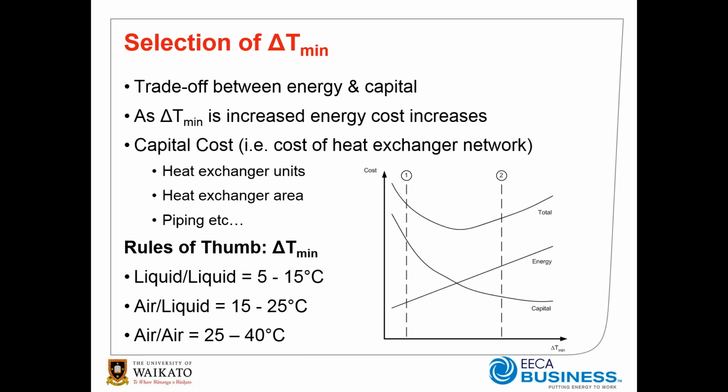From that point, we can then go to designing the network and sizing the duties of each of the heat exchangers. In this case, we would take an approach such as the log mean temperature difference, or another approach is the effectiveness-NTU method for sizing heat exchangers. Next year, we're going to look at holding some webinars that are specific to sizing and rating heat exchangers and also monitoring heat exchangers for fouling in order to detect when we should start to clean our heat exchangers.